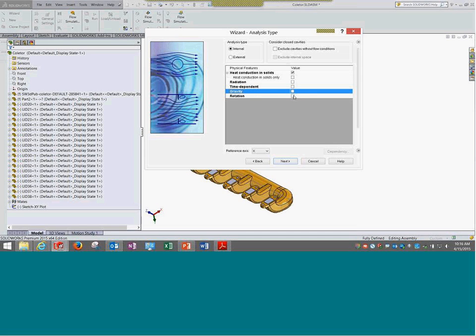Then we have the rotation. We discussed the rotating regions. If you want to simulate those, they can be played around with over here. The default is global, wherein the entire domain is rotating and there are some parts inside it which are static. There are a few cases where it could be applicable, but otherwise it would be more of local, that is sliding.